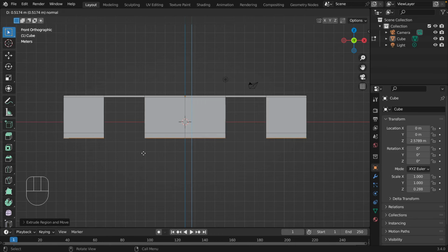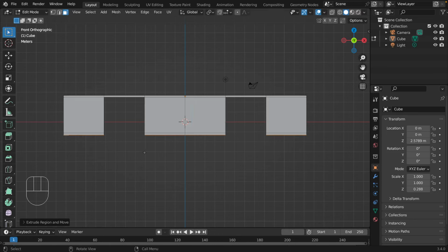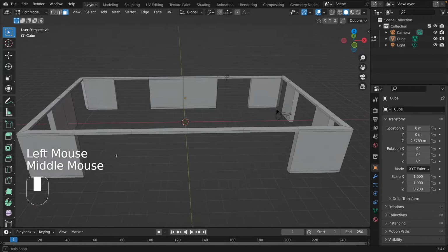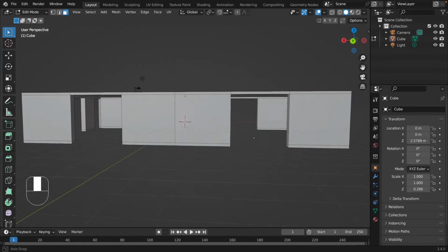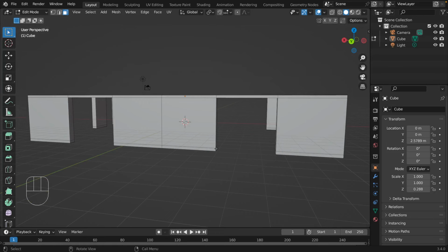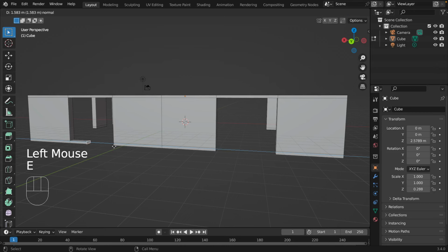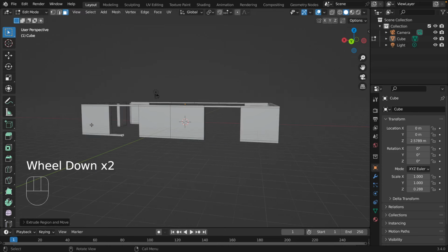Sometimes you might get a pretty thin area here, and then you can add more things by, say, extruding these faces or maybe this face. You can do that. So you can extrude maybe here, maybe half of it. Okay, so you can extrude here. You can even add in a little bit of rotation to make things even more interesting.